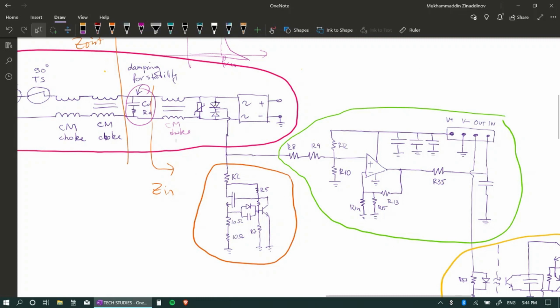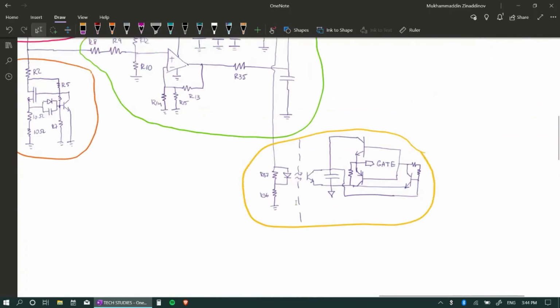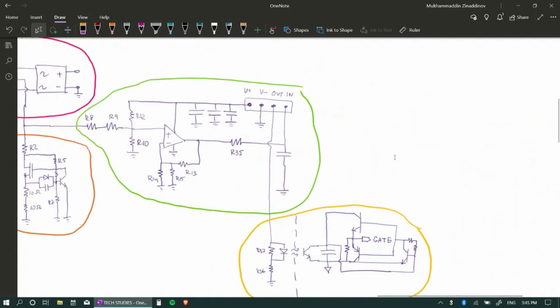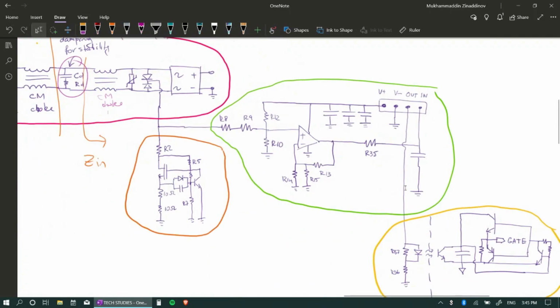So what is going on here? We have a half-wave rectifier. It then goes into this circuit. So it's doing a double duty of, first of all, powering this op-amp, and it also picked up with this non-inverting configuration of an op-amp. The output of the op-amp is filtered with this resistor and capacitor, and it goes into this microcontroller. So depending on the amplitude and the frequency content of this input signal, the microcontroller will adjust the output to keep it always at 12 volt DC.